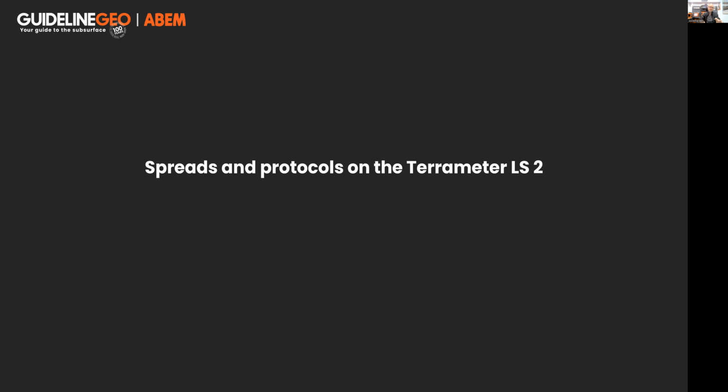It might be that your 3D survey is on a very specific target. It might be around a structure. It might be on the face of a dam. And so the layout that you would need to make is constrained by the space available to you. So you would more often in a 3D survey want to build something custom than you would in 2D.